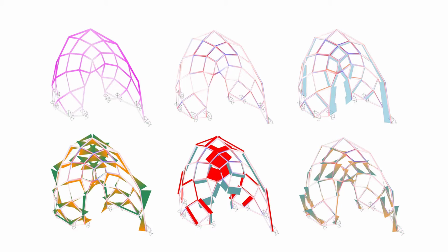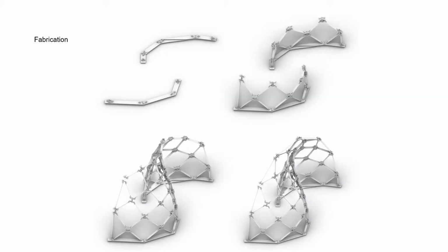From the analysis, we realized that the nodes behave semi-rigidly, which offers more stability in the assembling process, and it's compatible with a wider range of networks. Regarding the fabrication, to control the assembling process, elements indicating the structure's footprint have been considered in the design process. By laying these base structures, the rest are woven gradually towards the top of the structure. The assembly of the bars and nodes is done manually, and the construction process took less than 1 day.